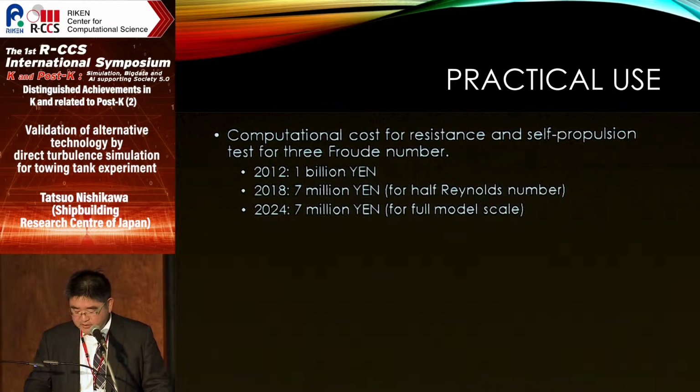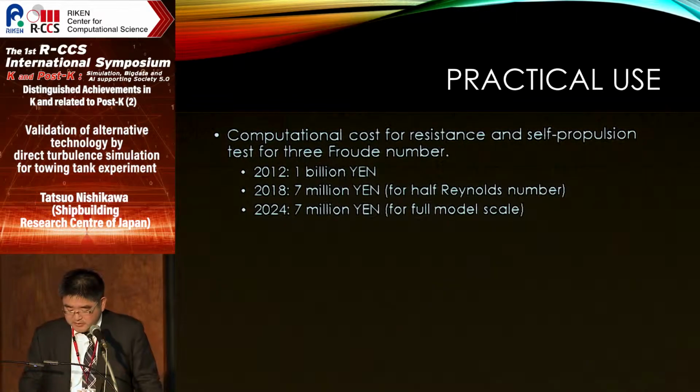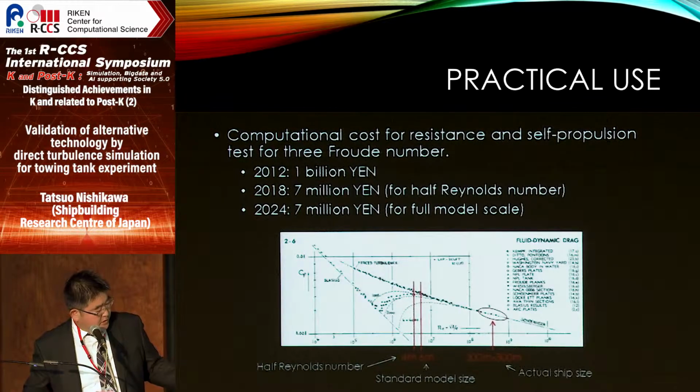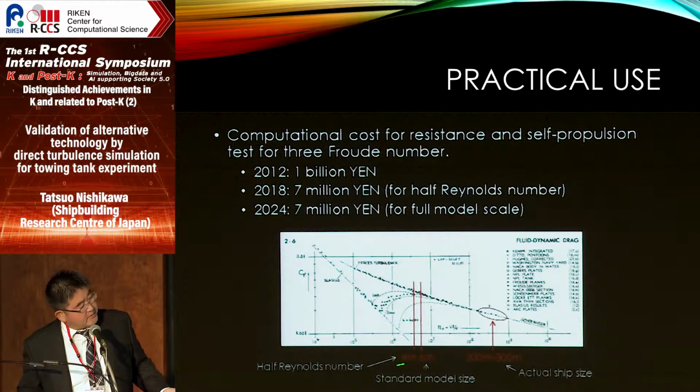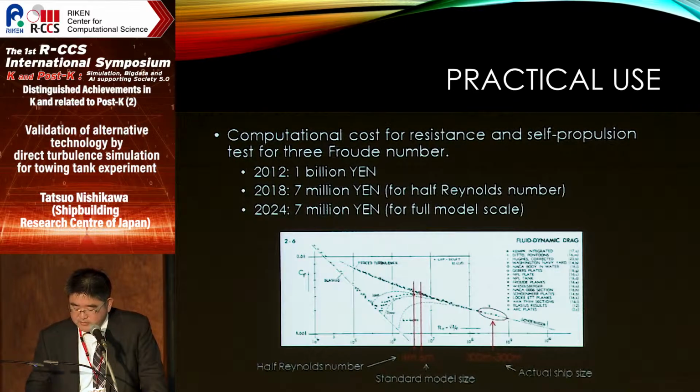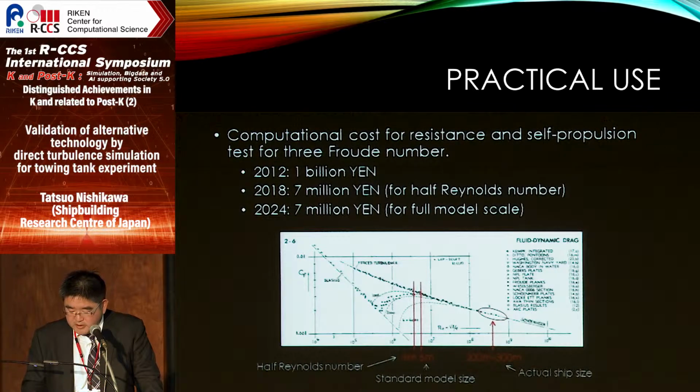And unfortunately, our customers misunderstand that the closer the model size is to the actual size, the more accurate the prediction is. But the difference between 4 meters here and 6 meters is much smaller than the distance from 6 meters to 300 meters. They mix up the experimental errors, such as model manufacturing error and the larger disturbance compared to the smaller measurement force for the smaller model, which simulation doesn't have.